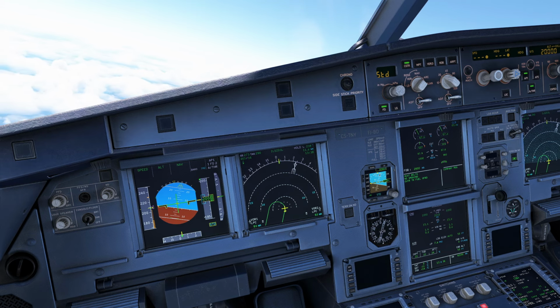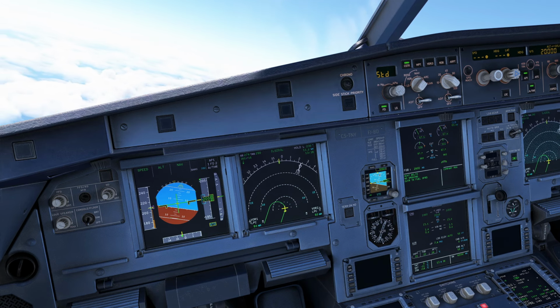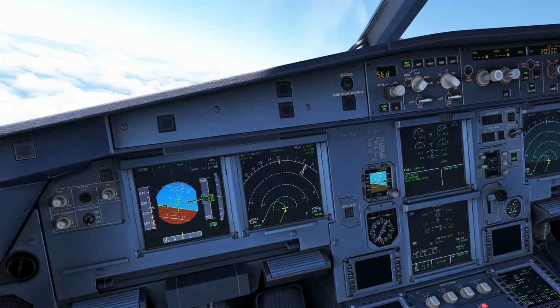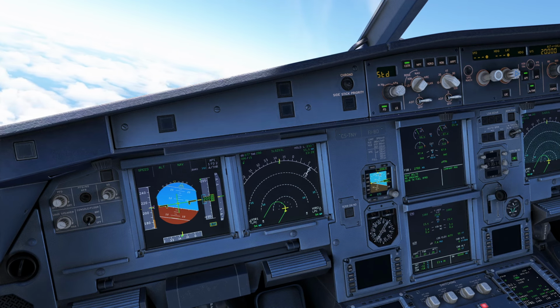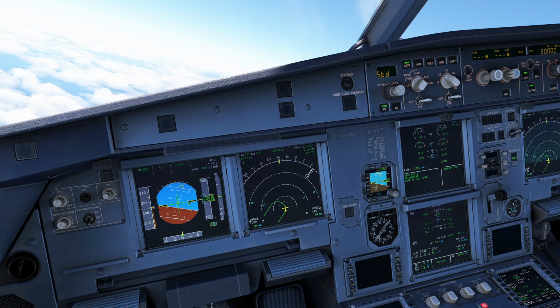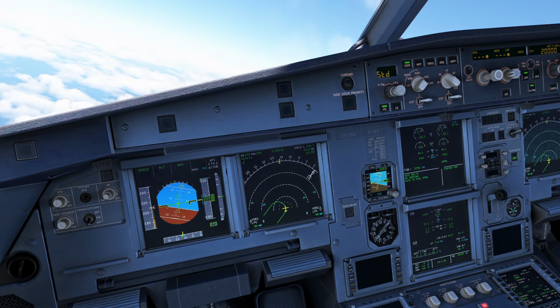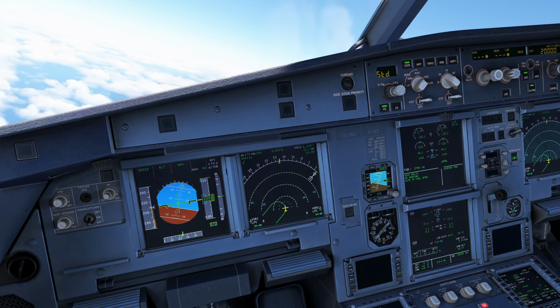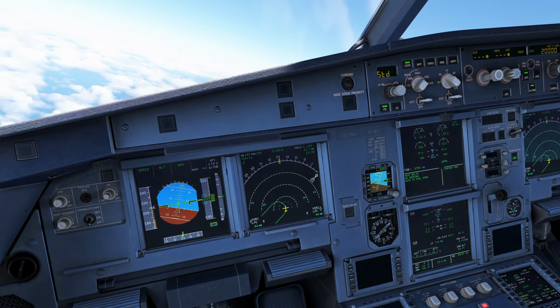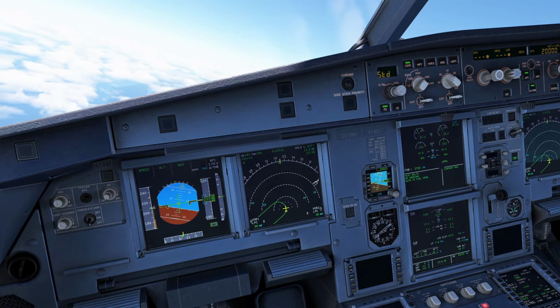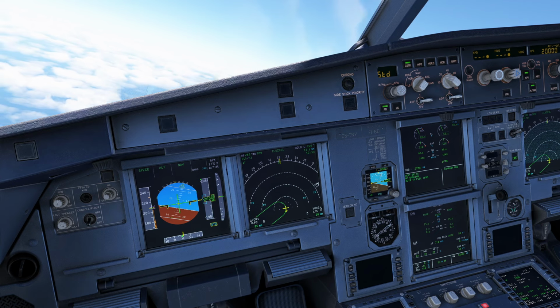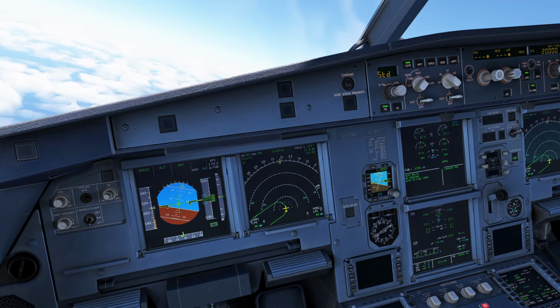I told you, some SOPs in some airlines instruct pilots to stabilize at 1500 feet, not 1000, especially when you are flying a heavy aircraft, such as A330, A340, A350 and A380. In most cases, this equates to the aircraft being in configuration 1 and at S speed at the final descent point that we talked about already. This is the preferred technique for an approach using vertical managed guidance.